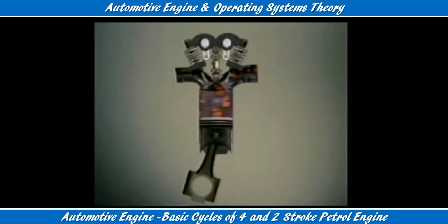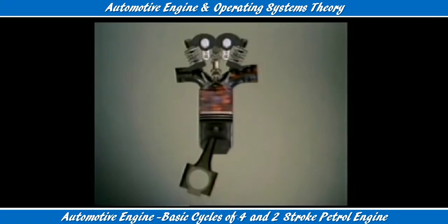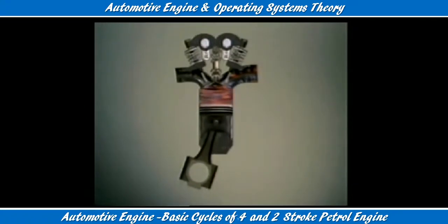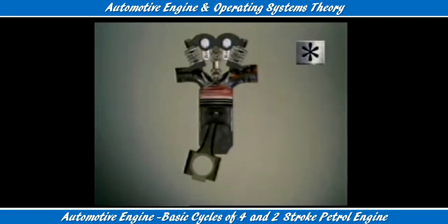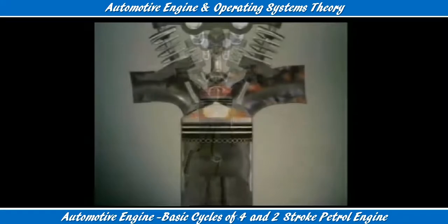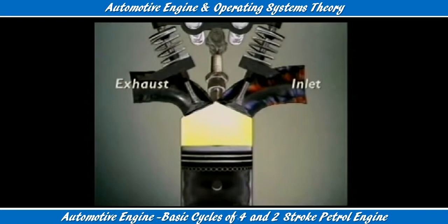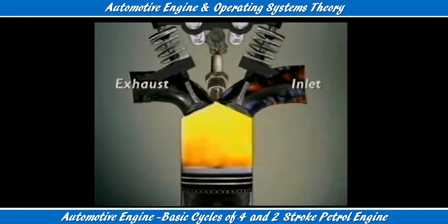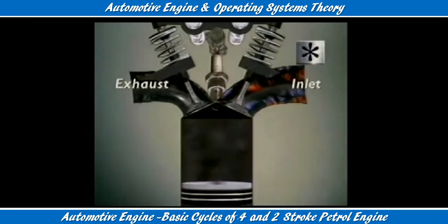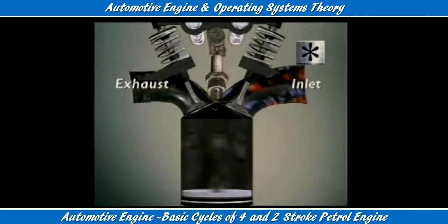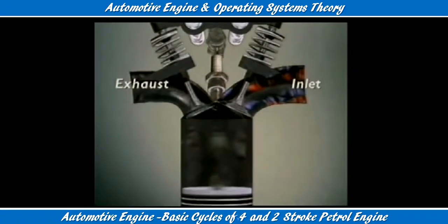Both valves stay closed as the piston leaves bottom dead centre. The piston moves up, squeezing the air-fuel mixture into a smaller and smaller volume, which compresses it. That makes its temperature rise and that makes combustion easier. Just before the piston reaches top dead centre, the next key event occurs: ignition. Burning, expanding gas generates the force to push down the piston. This is the power stroke that drives the engine.